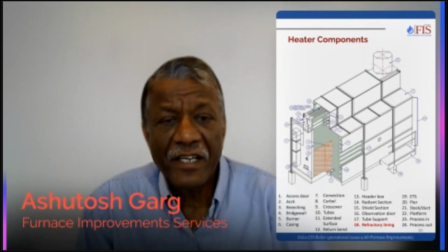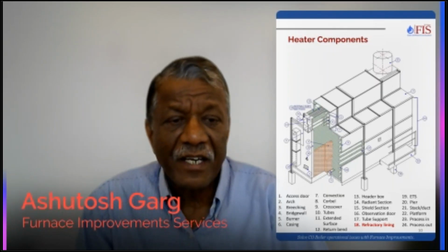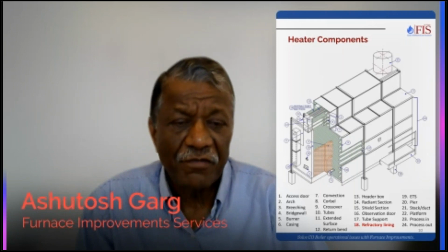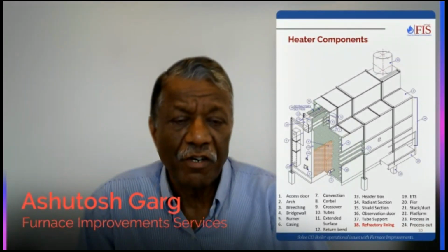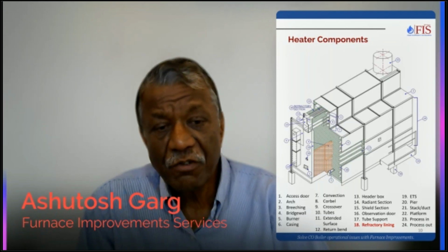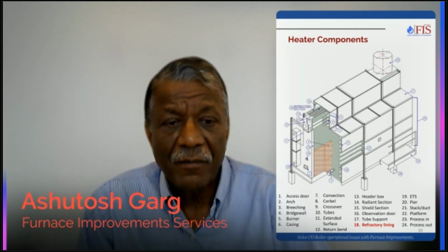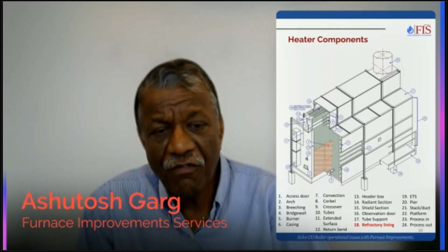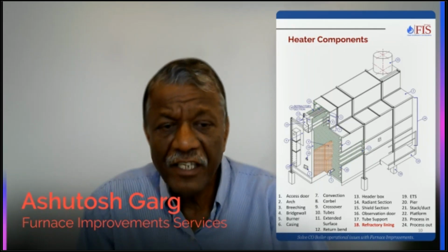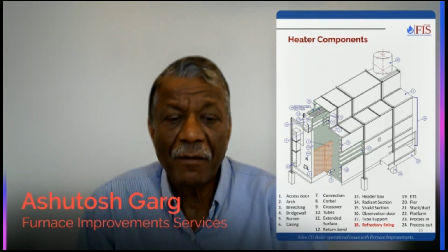Breeching, stack, end tube sheets, header boxes. So refractory lining is practically everywhere. And this one even has a gravity wall, maybe for a poker or for some special units. That is a special thing as well. There have been cases where this refractory wall fell down or started inclining; those types of problems have also happened.